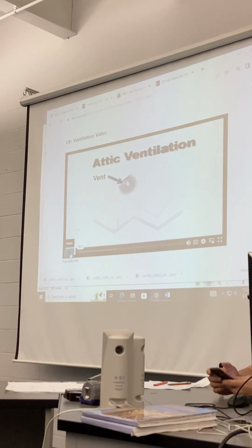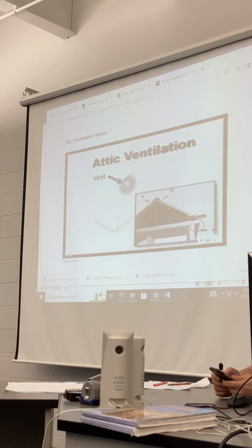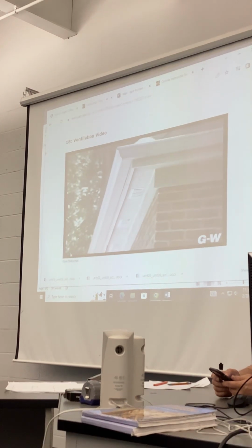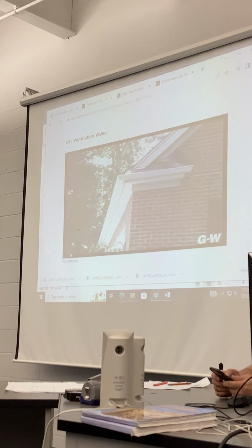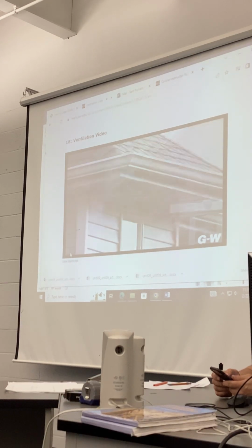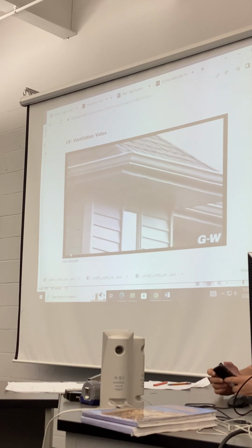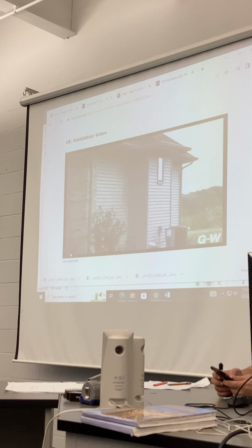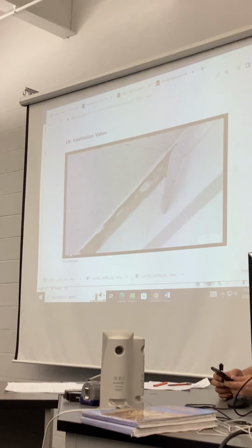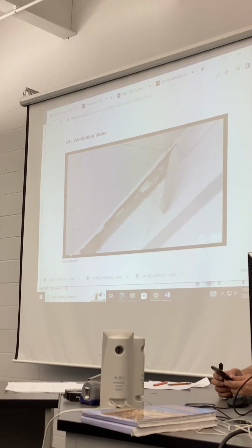It may seem like attic vents defeat the purpose of insulation, but they are a vital part of keeping fresh air circulating throughout your home. An unventilated or underventilated attic can trap heat in the summer months, raising the home's indoor temperature by several degrees and putting a strain on the air conditioning system. During the cold winter months, poor ventilation can cause warmer air trapped in the attic to condense under the roof decking, possibly causing minor water damage.